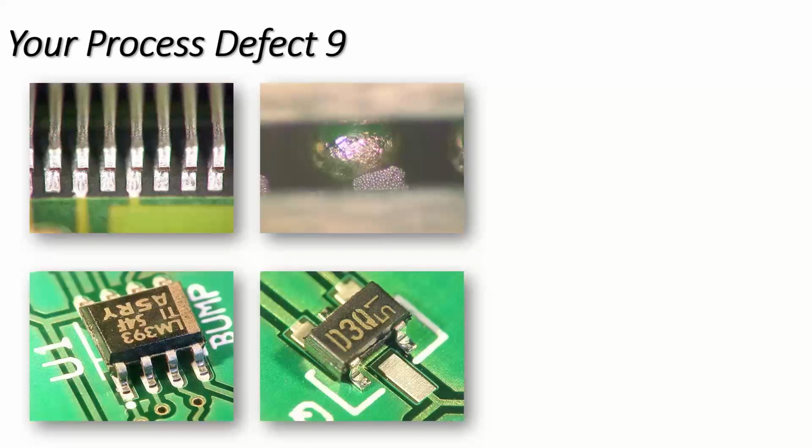Next one: how to reduce voiding with thermal parts. Well, if I could briefly run through that: first of all, obviously paste and profile. Those are the 2 key things. You've got to experiment and get the best paste combination and profile to get the best results. Next, look at stencils and get your design right. Do not get solder going into vias, because that inevitably will give you more voids.